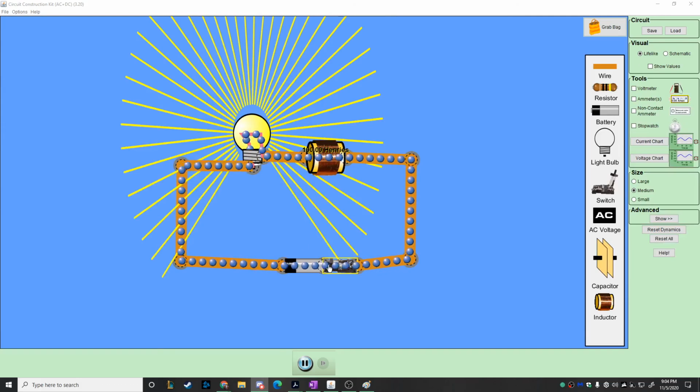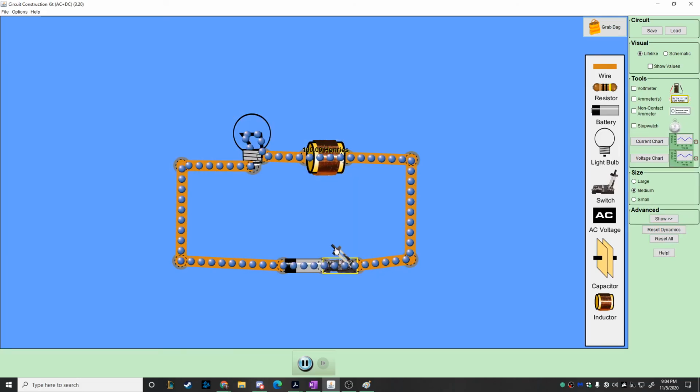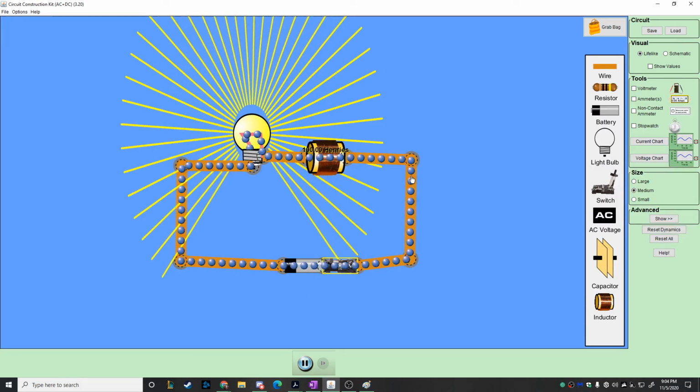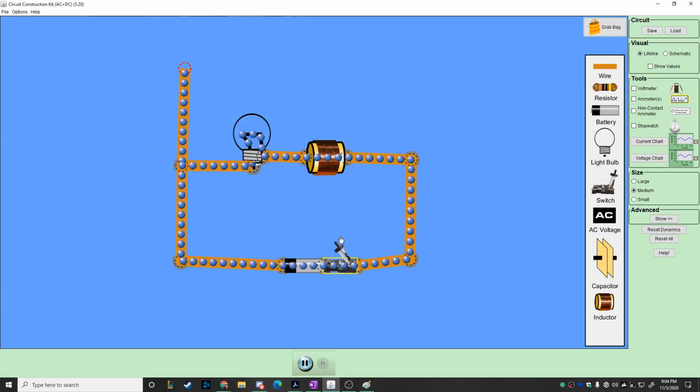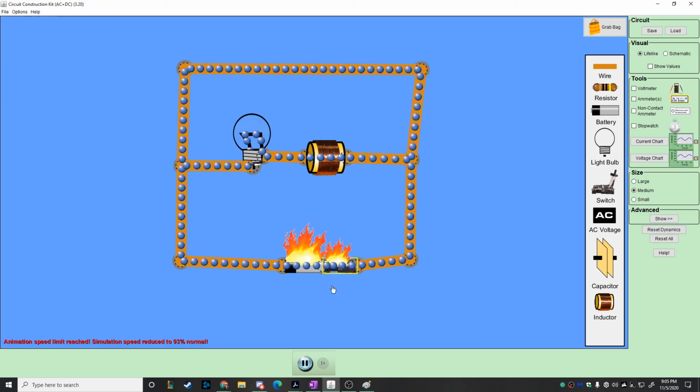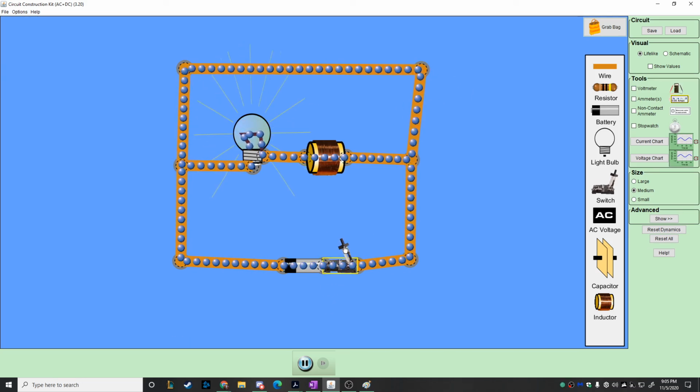We can do that, Ash, except right now, it can't power the light. Why can't it power the light right now when I open it up? No circuit, right? So what do I need to do to allow that to happen? I need to basically complete a circuit on the top, right? So let's do that. Let's open this. Let's give it a path so that the inductor can do exactly as you're saying there, Ash. So yeah, I knew that was gonna happen. We need to add a resistor into the top here, so that it doesn't burn the circuit up.